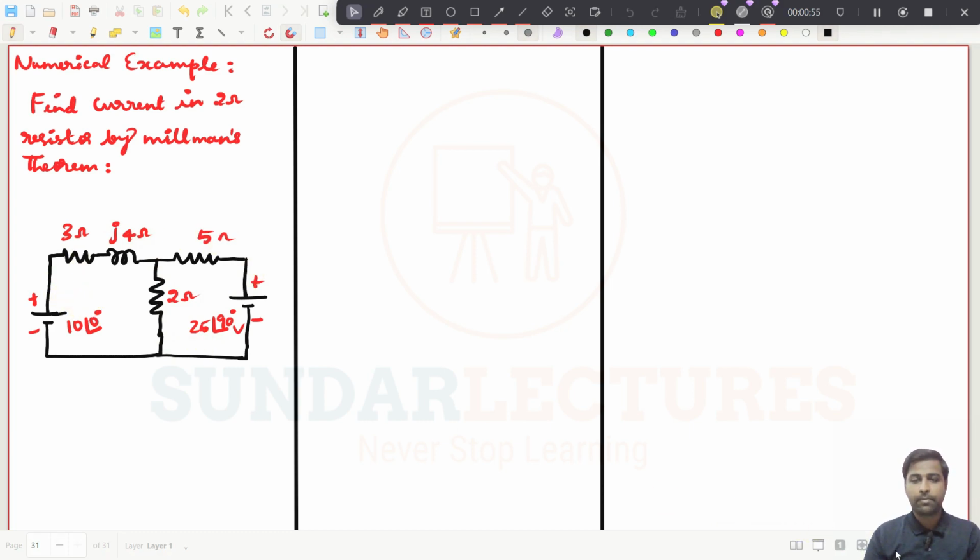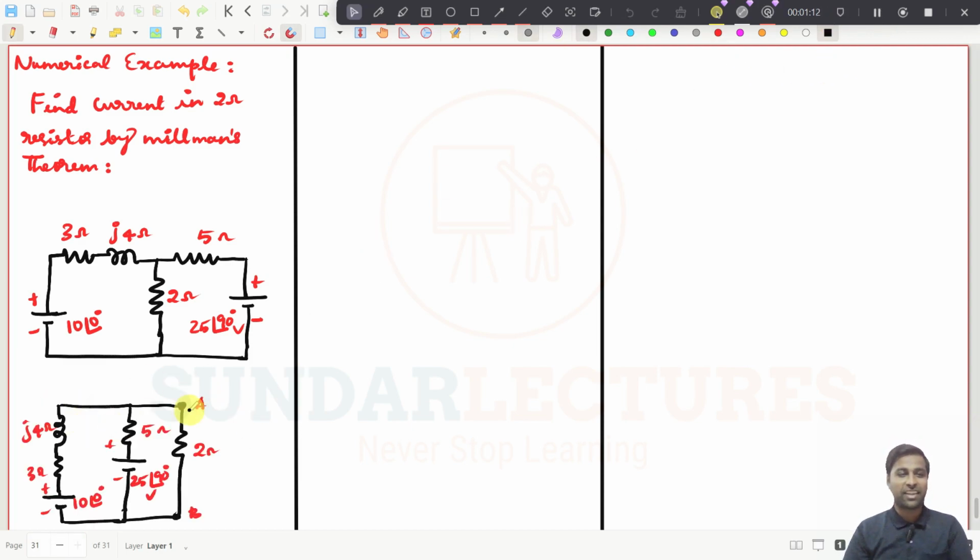See, for example, if they are giving you a problem like this, then what you need to find is the current in the 2 ohms resistor. Then you redraw the circuit. How will you redraw this circuit? I will redraw this circuit now. See, I have redrawn this circuit like this. Why? Because I want to find the current through the 2 ohms resistance. So I bring it to point A and point B, and these two are connected in parallel, right? So I have drawn like this.